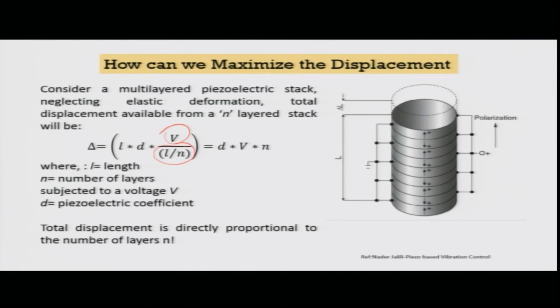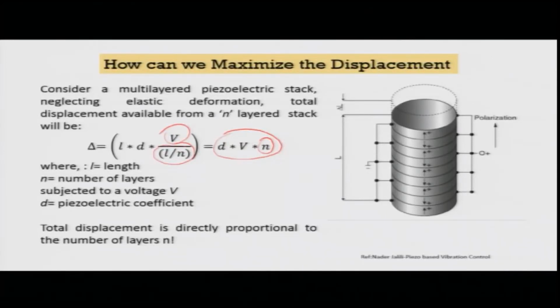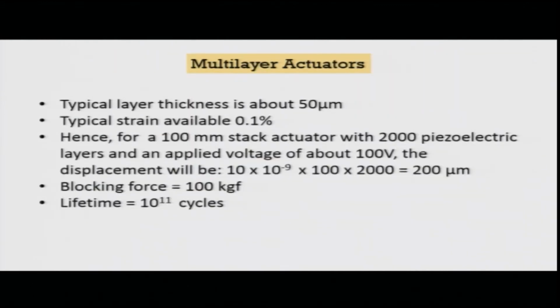That means, the finer you are going to make, the higher it will be. You can see that your deflection displacement is directly proportional to the number of layers. So, if you can cut your disc very thin, you are certainly going to get advantage out of it. Now, cutting a thin piezoelectric disc is not very simple. I would later on tell you that this is what actually brings us to the domain of what you call MEMS systems. To make it enormously thin, something like 10 micron to 100 micron kind of thickness, you need special technologies to do that.